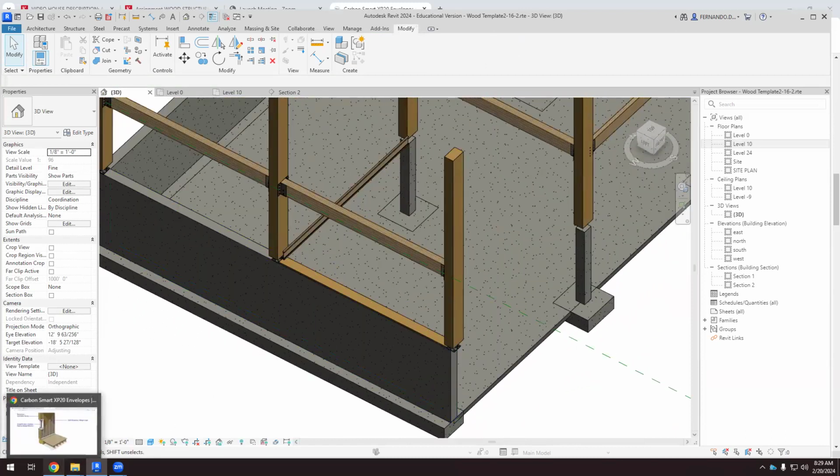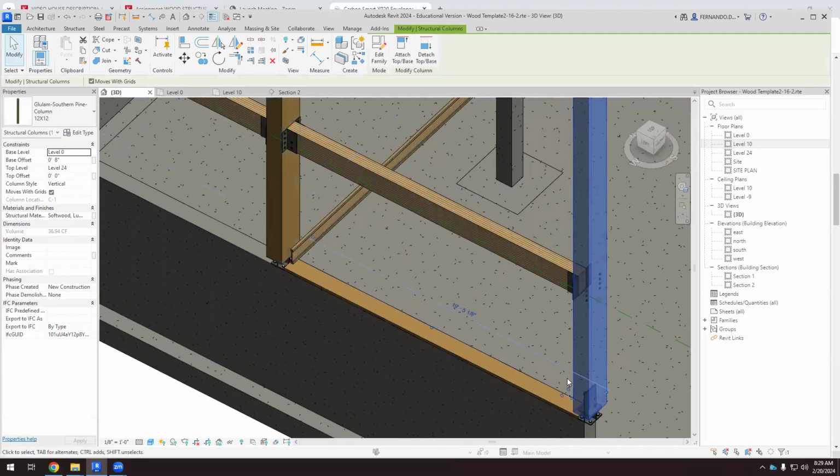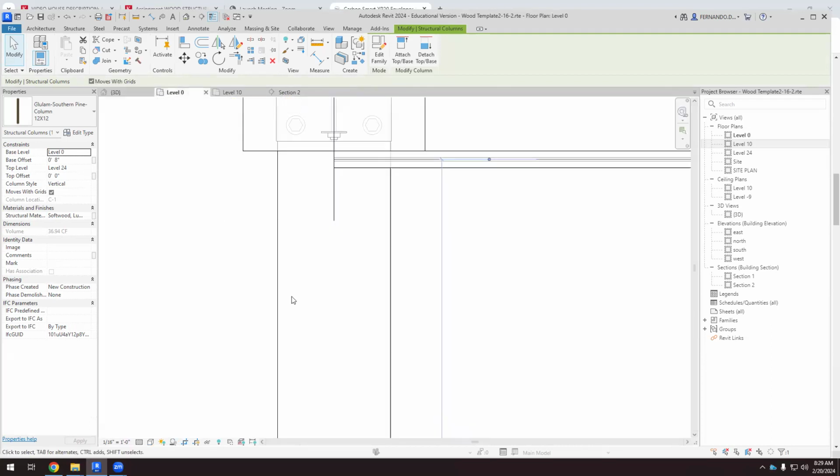And now what's the distance between joists? It's not specified, but it's a decision that we have to make. Usually, the distance between these joists is around 16 inches. So the standard is that we have 16 inches between these joists. But in this case, we have to abide by the distance that we have between columns. Okay, so what can we do here?